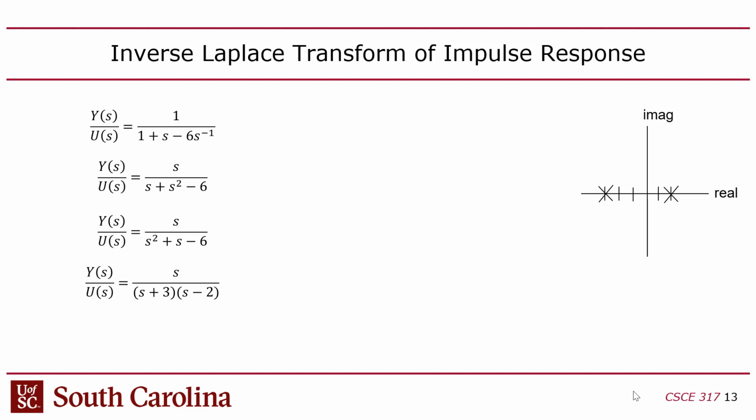And because of this plus 2, you end up with a pole that's outside of the left-hand side of this plot. And so for that reason, it's an unstable transfer function. Now, again, it's not necessarily always unstable. You can hit it with certain frequencies where it will be stable, but there are some frequencies that you can inject in there that will cause it to be unstable.